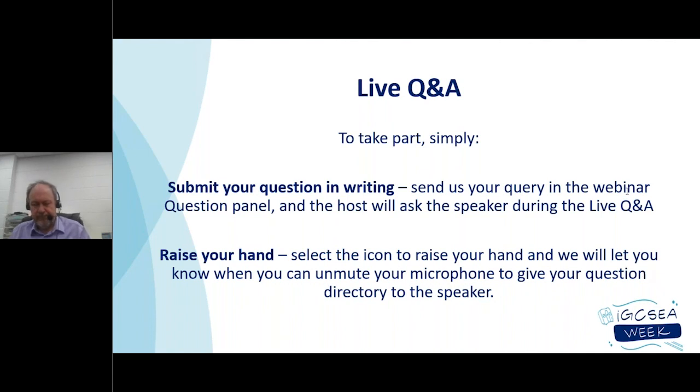Yeah, that's a great question. I would say if moisture is not changing the surface, so if it's, let's say, a hydrophobic surface, you add water, you're going to get very little change. You might just see, like Daryl said, a small decrease in the surface energy. However, for a lot of real world materials, moisture changes the properties of the material. It could open up different functional groups.